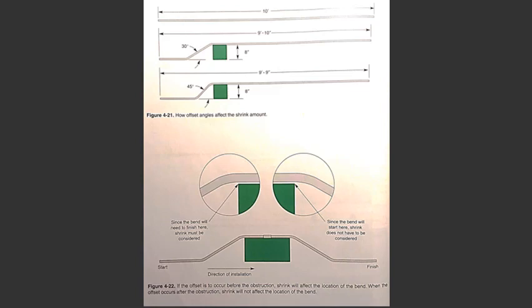Professional tip: keeping bends aligned when putting 2 bends in a piece of conduit. They must be in perfect alignment, so the conduit will lay flat against the wall. If one bend veers to the left and the other veers to the right, the conduit will not lay flat. To maintain alignment, find a seam in the concrete or tile floor, line up the first bend and the bender with the seam to keep the second bend properly aligned.